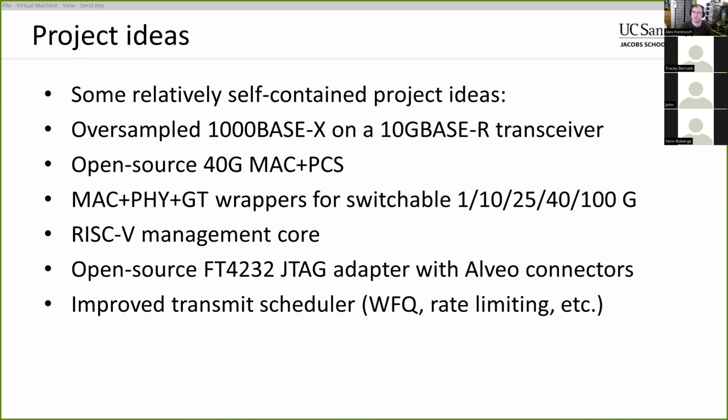You're not getting that mixed up with the MSP430 that's on the board, right? I think they have both. The MSP430 microcontroller sits on the board, and they also have the MicroBlazes. That's not on the FPGA, but it's used for board management stuff. Right, and that would have to be flashed separately from the FPGA. And I think when you update the Alveo shell, it will potentially update that as well. I think they have something in for both. Not sure how they implement it. Might be worth taking a look at.